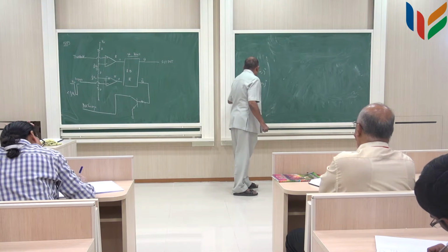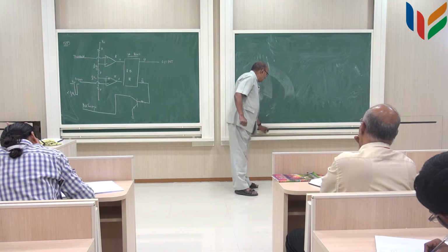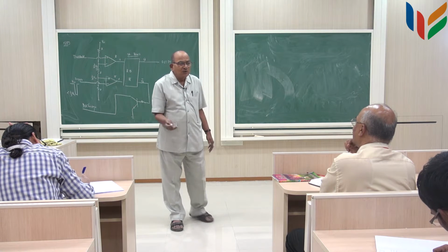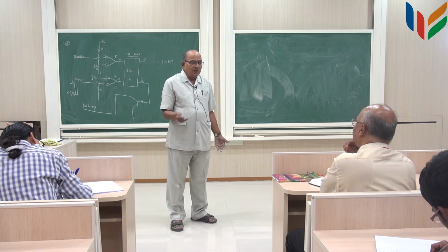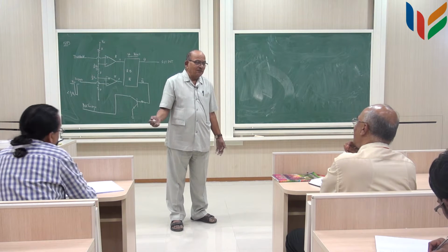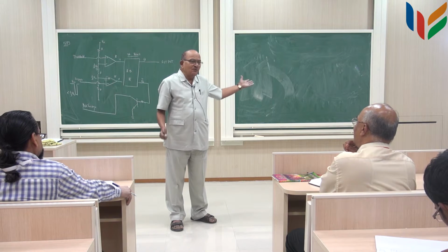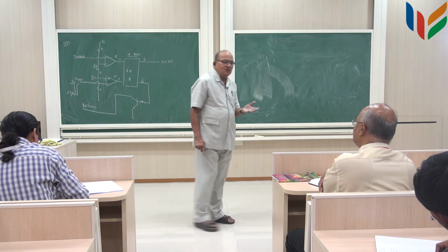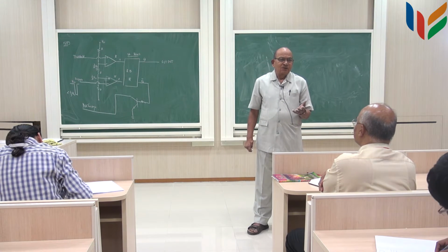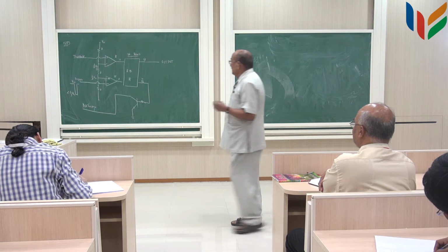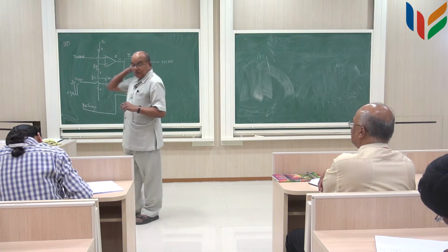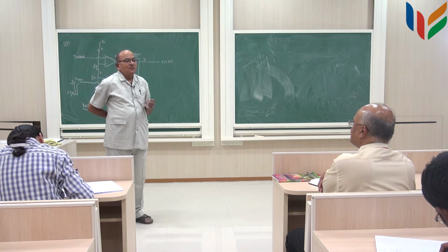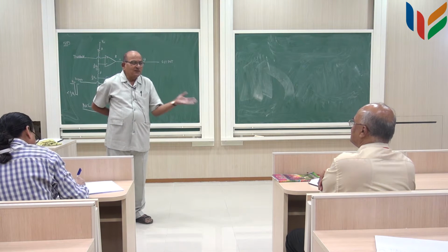Once I know how to do multiplication, then I can also find out how to find the average value of a time signal, right. You take the signal, put it in an integrator, and that will give you the average value. Integration we know, using an op amp, putting a capacitor and resistor, we get an integration. So, we know how to do integration, we also know how to do differentiation. These time dependent operations like integration and differentiation I know how to do.